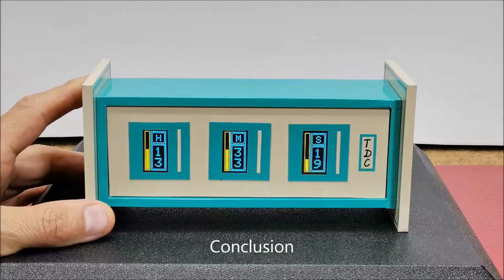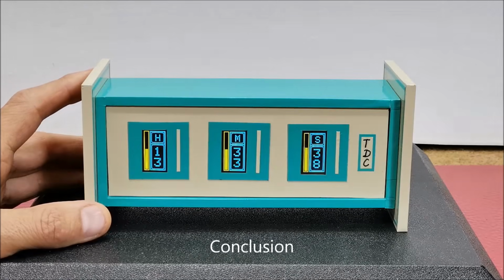And finally, a short conclusion. This do-it-yourself clock successfully uses an I2C multiplexer to show the time across three OLED displays, complete with clever progress bars that visually track the elapsed time for the current minute, hour and day. Also, the code can be easily modified to customize the visual look of the OLED screens.